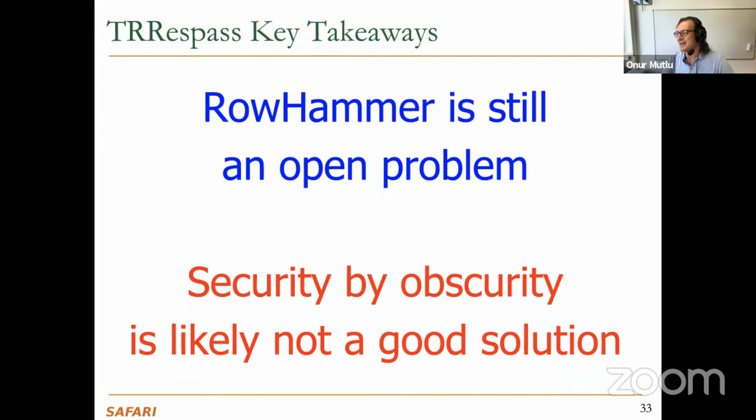I think we will talk about this more when we get to not just RowHammer, but also processing in memory, for example, right? Processing in memory has not been enabled for 50 years, even though there were very good arguments for it. But finally, manufacturers are trying to enable it. Maybe the manufacturers are not good at understanding the security implications of what they design, basically. I think that's my best explanation to it. Plus, there are business implications, of course. It increases their cost. And also, the DRAM interface limits what you can do today. We'll talk about all of this.